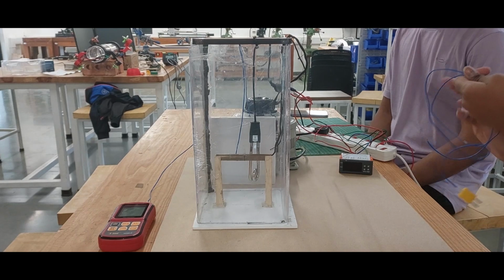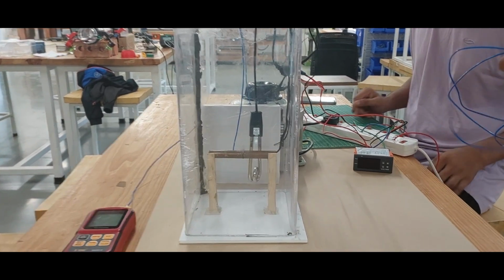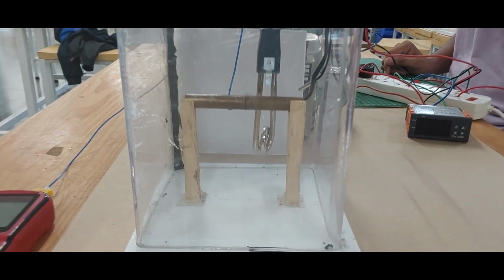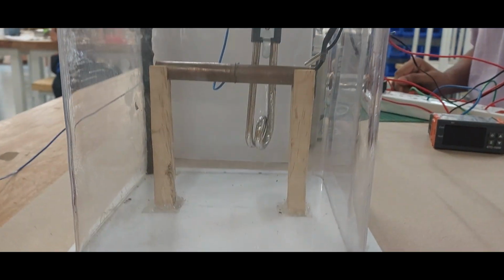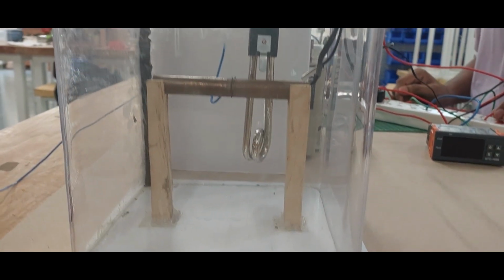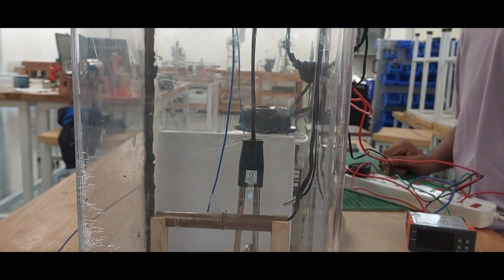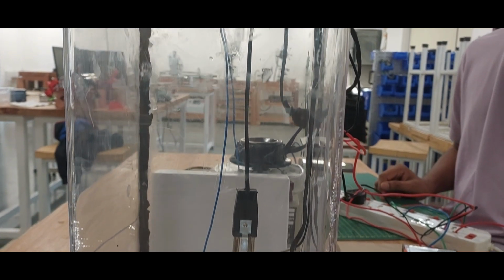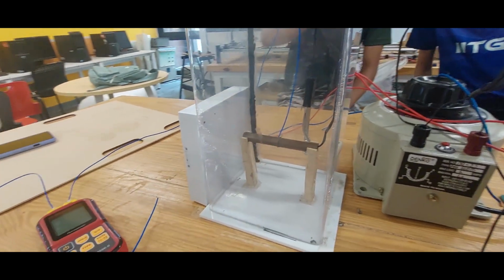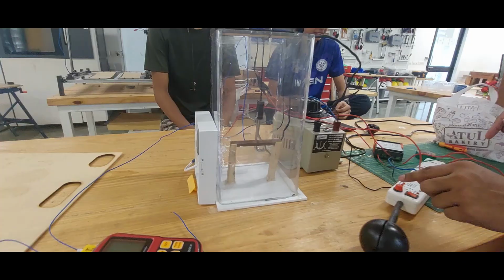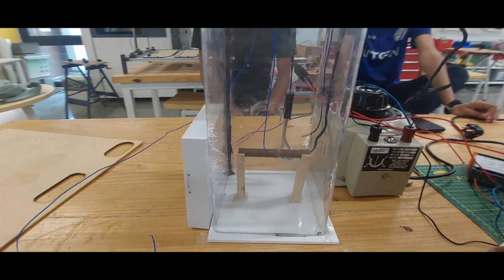The cylindrical rod shown here acts as the test surface where pool boiling occurs. The choice of copper, aluminium or stainless steel allows us to investigate how different materials influence the boiling process and heat transfer characteristics. The cartridge heater is inserted into the cylindrical rod to provide controlled heating to the rod surface. This heating element allows us to maintain a specific test surface temperature independent of the water temperature. The variac shown is used to control the power supplied to the cartridge heater.